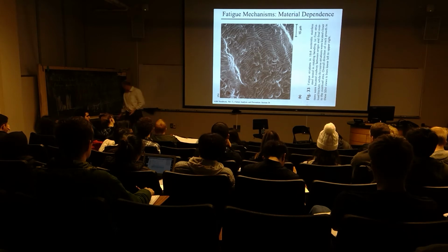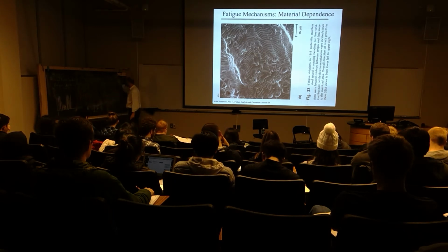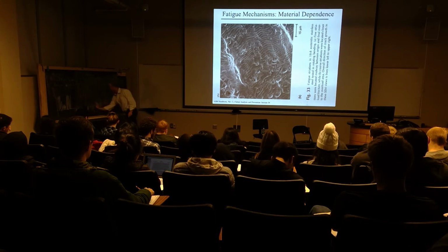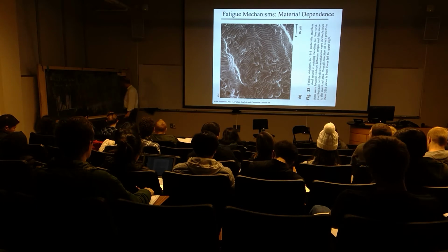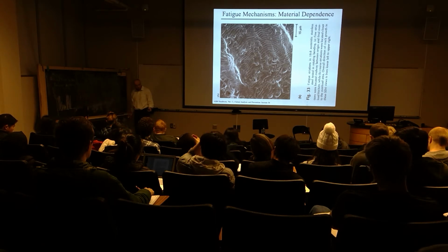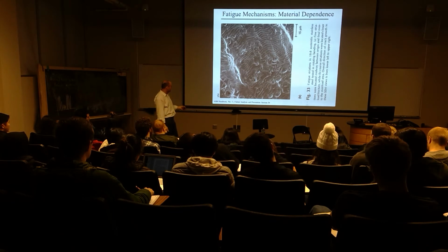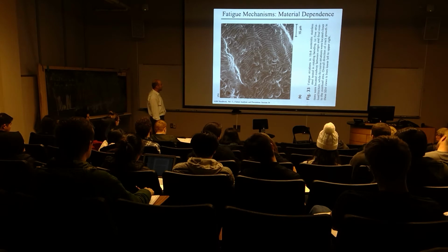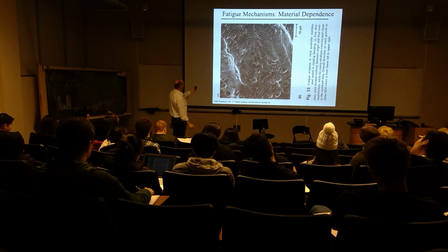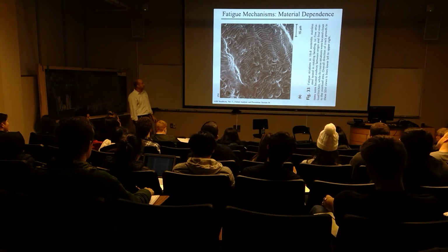Okay, so what can you do when you have striations? Let's say, for example, we have a case where we're asked to look at something that's taking place in a material, and we have a good example of a fracture surface with striations. So here's one. This is figure 33, and this is an 18-8 austenitic stainless steel, and I have the striations that are very well defined. I know the direction in which the crack was growing, and what I have is an area where the striations all look about the same common spacing.